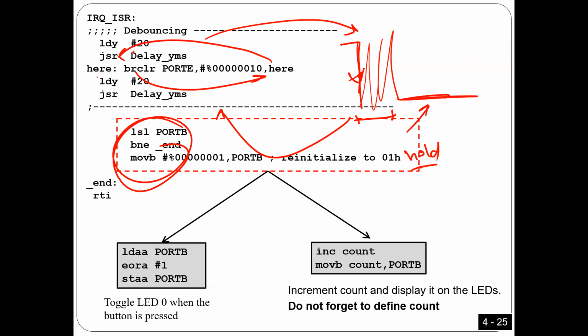Okay. I'm here using port E, right? Because IRQ is actually connected to port E pin number 1. This is IRQ. Is that okay? So here, port E.